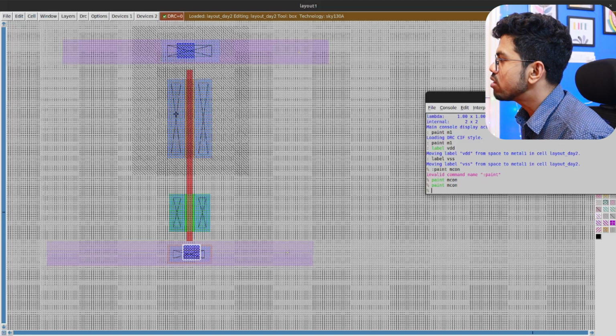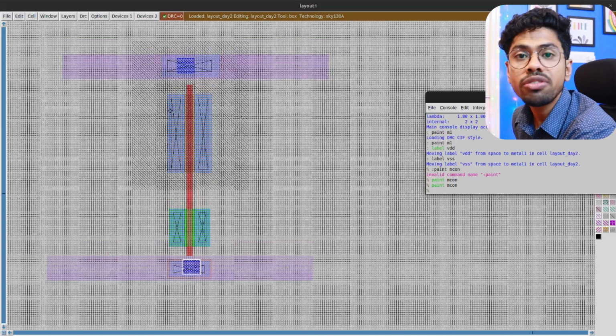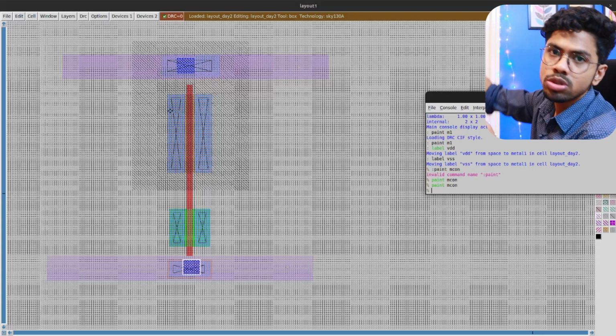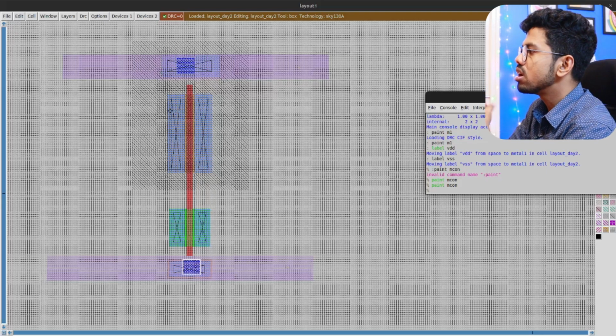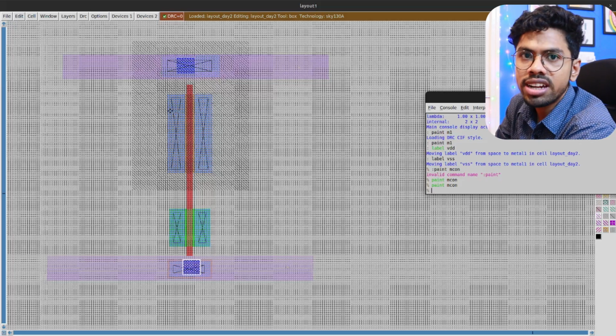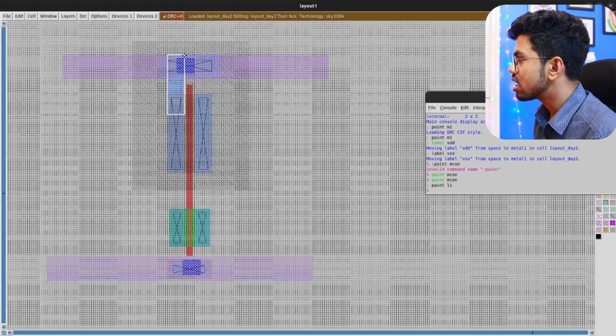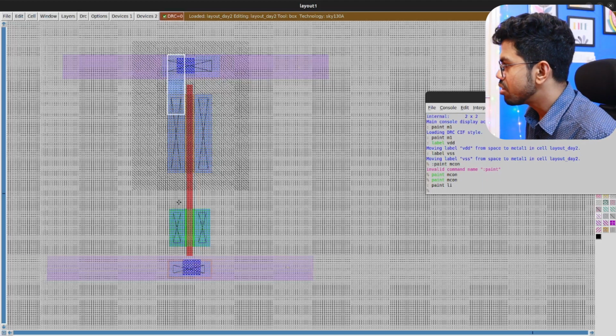Okay, so now this is your source, this source needs to be connected here. So how to connect it? You have many metal layers, you can use metal 3, metal 4, any metal layer, but why use those metal layers? We can use them for other tasks outside this block. So we will use the lowest one, and that is LI only, and that's why local interconnects are defined, LI. Luckily I hope there is no DRC yet, and we will do the same thing for this one also.